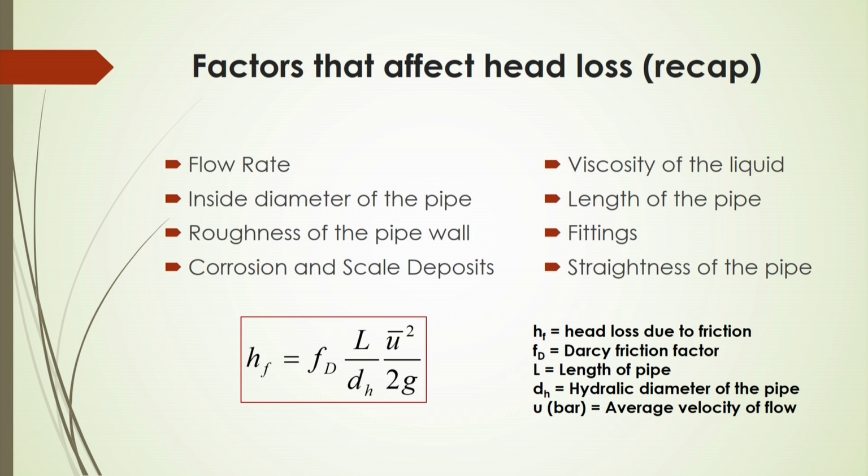It may happen in non-regular shape pipes, with different geometrical shapes, like a square cross section, rectangular cross section, or any other oblong shape of the pipe. And in general, we consider the equivalent diameter of the pipe as the hydraulic diameter. Already we have defined how this hydraulic diameter is obtained.